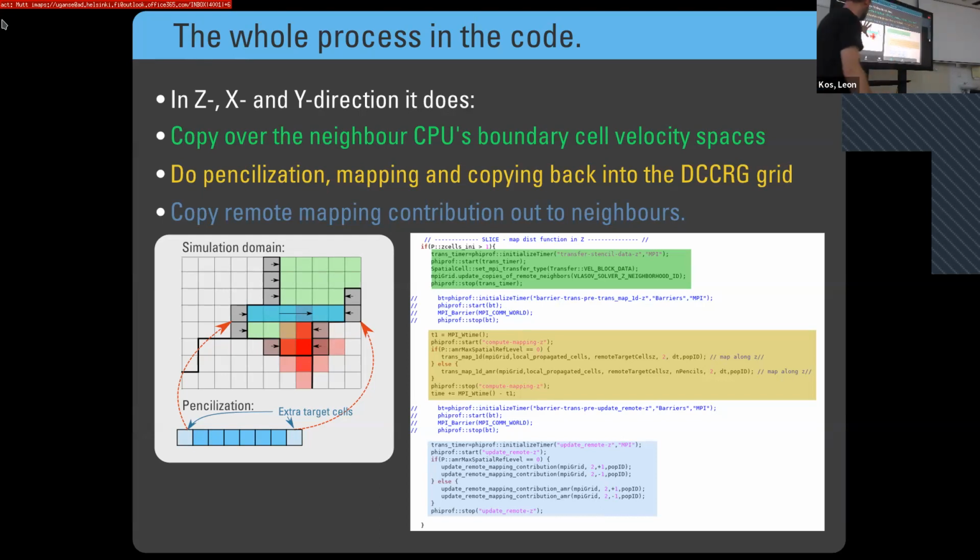What I've skipped in this easy illustration is if we have inside of our domain here an AMR level transition. Normally we do not build a continuous pencil throughout this, but we only do a maximum of one level step, because otherwise our pencils get split so small that it's not actually an efficiency gain. So we just stop the pencil, do one here and do one there.